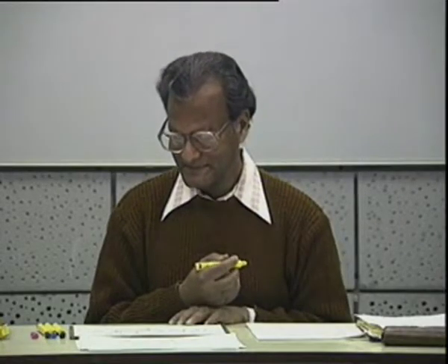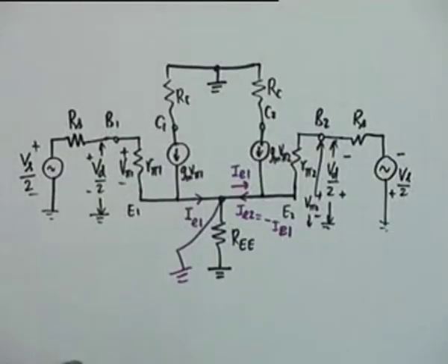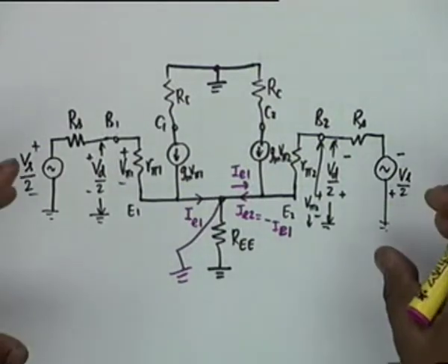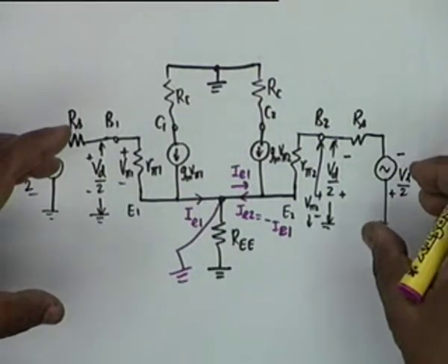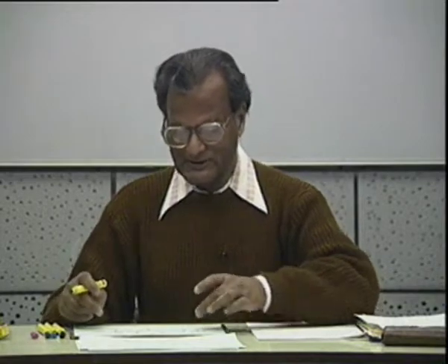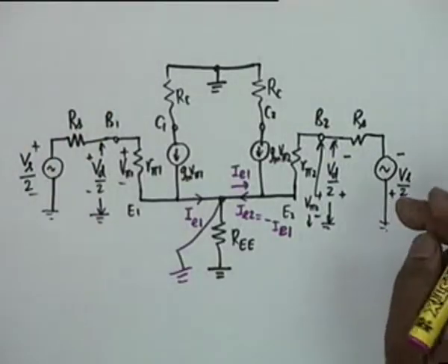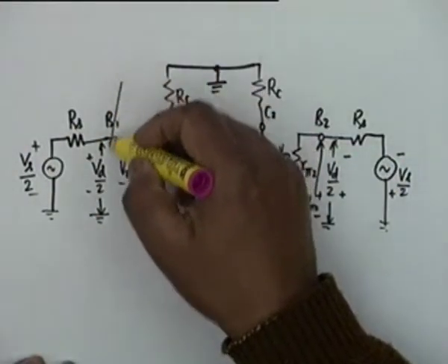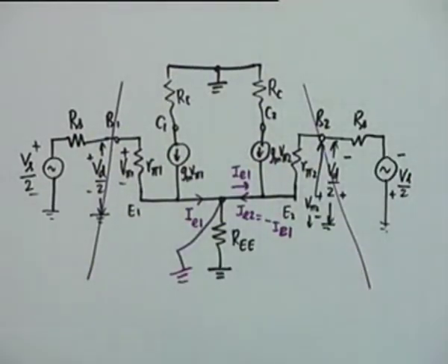Sir, so do we need an RS there? Yes. Because we are applying signal at only one base and you said the other base is grounded. This is the way of looking into a single voltage applied between the two bases. As I said, I decompose this signal voltage into two voltages. So that means the resistance of the signal source also. This is only a conceptual simplicity.